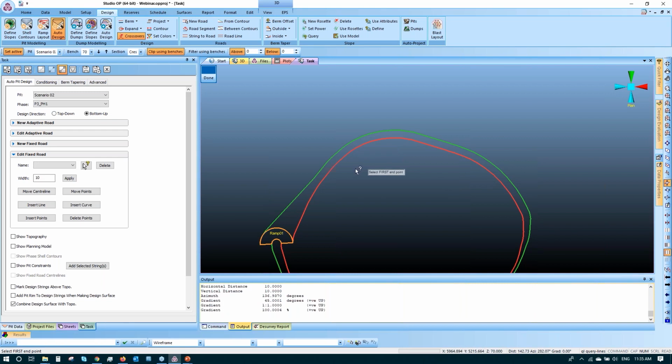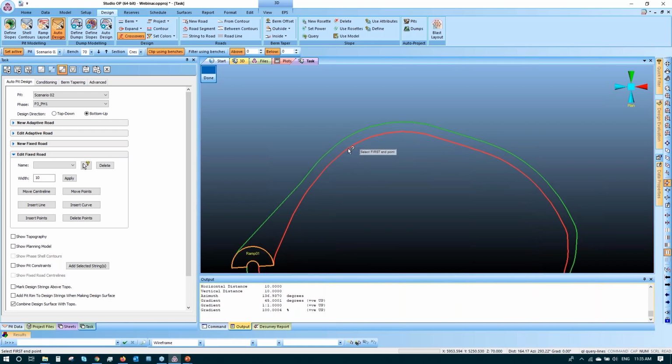One important thing that I would like you to know is that the azimuth, if it's in the top-down direction, has to be measured from inside to outside. So, for example, here I will measure from the crest over here to the toe over here. And in my results here, I will have an azimuth of 324. So this azimuth is within the range that we are modifying. So let's check the other one here. It is also 336, also within our range.